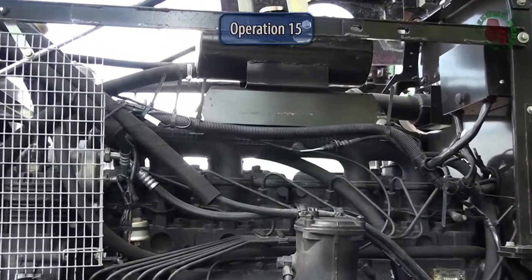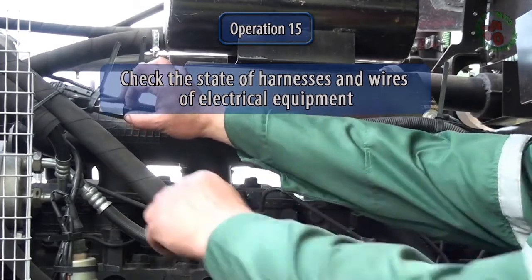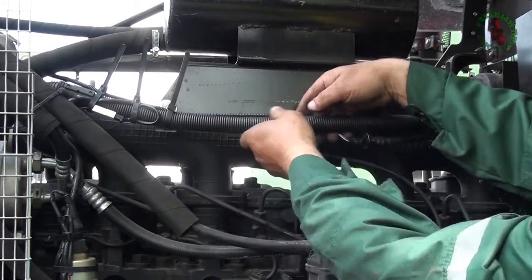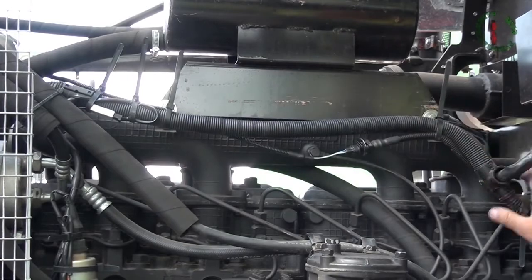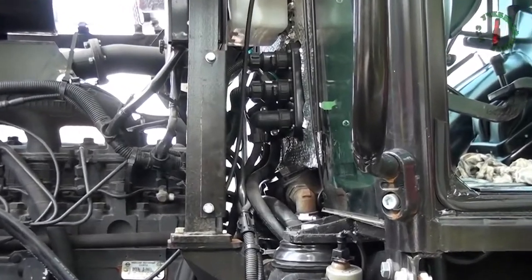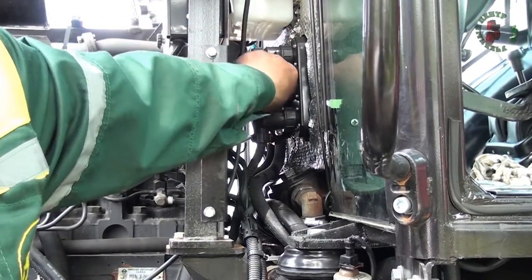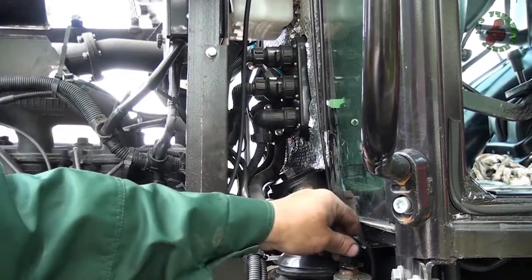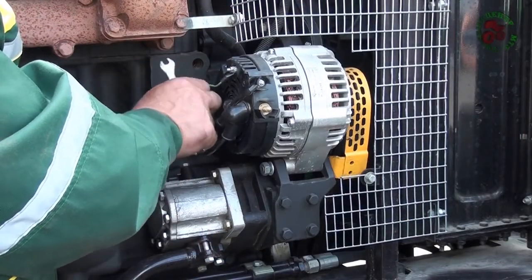Operation 15. Check the state of harnesses and wires of electrical equipment. Check the condition of wires and harnesses in the engine compartment, at the area of the front part of the cab, and visible parts in respect of melting, chafing, and destruction of outer parts of isolation. If there are the above listed defects, restore damaged areas with adhesive tape and eliminate the cause of damages.